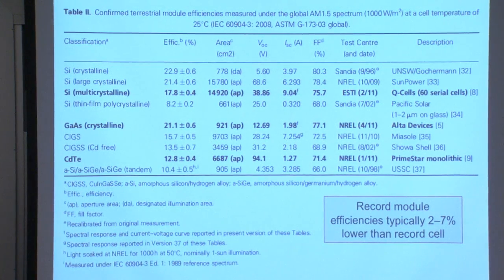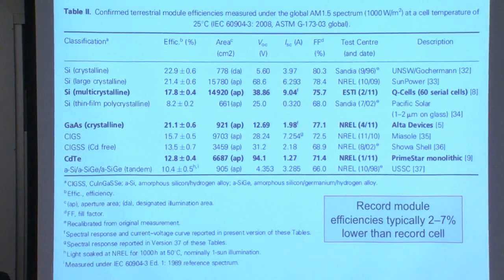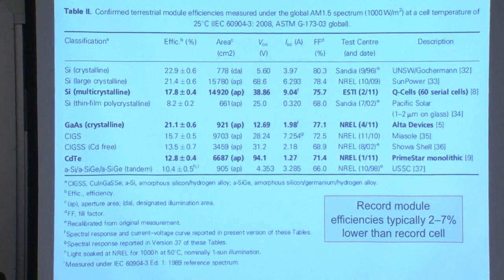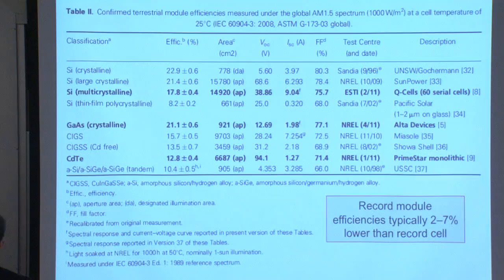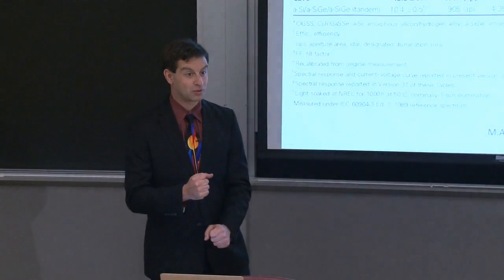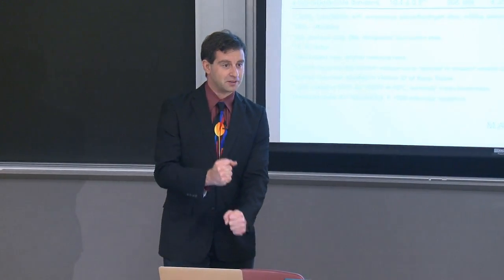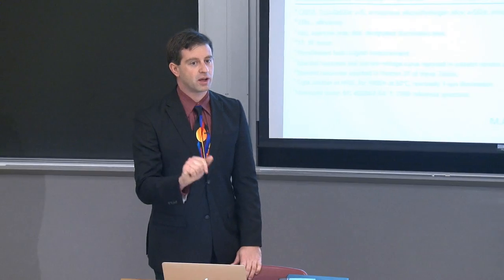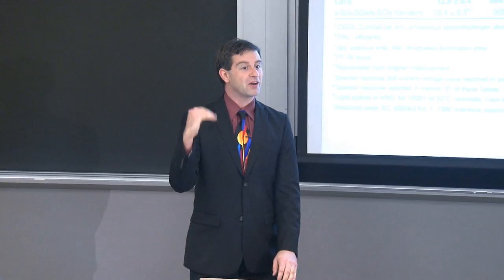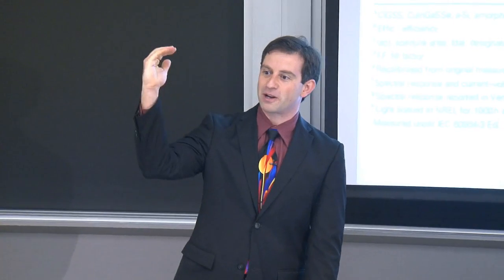Inhomogeneities, exactly. So if you have inhomogeneities in thickness or in composition or even in surface quality from region to region in that large area, you're likely to reduce your performance. One analogy, since I know many of you are mechanical engineers, is when you're doing tensile tests with ceramics or brittle specimens at room temperature. You pull on your specimen, and you obtain a certain fracture stress. You then take that smaller piece, pull again. Now the fracture stress is higher. Pull on that smaller piece that broke off, yet again, and now the fracture stress is even higher.